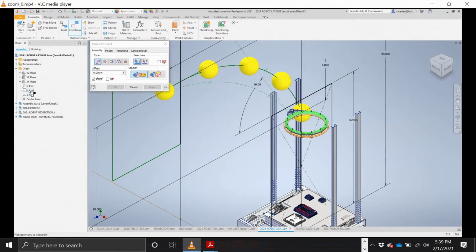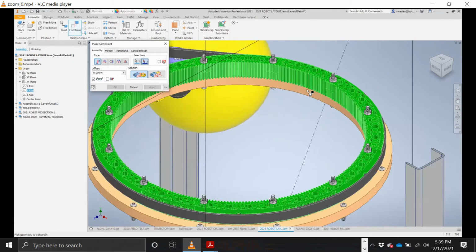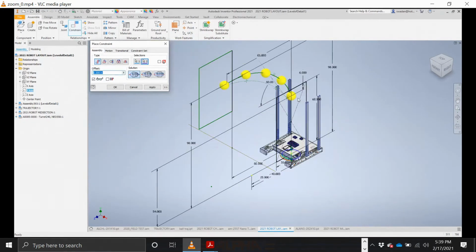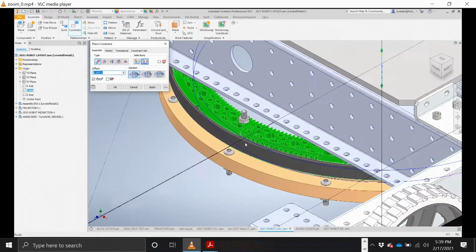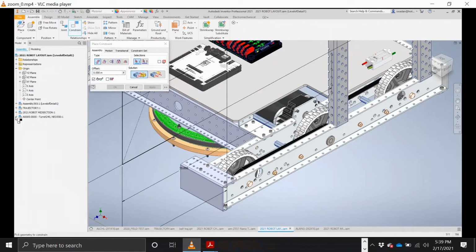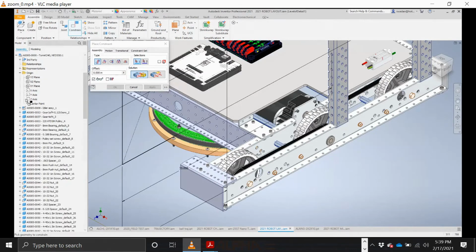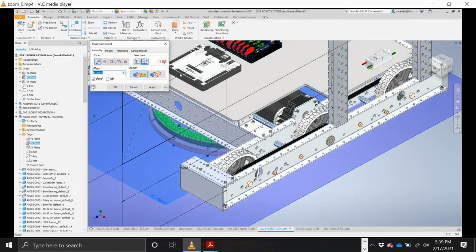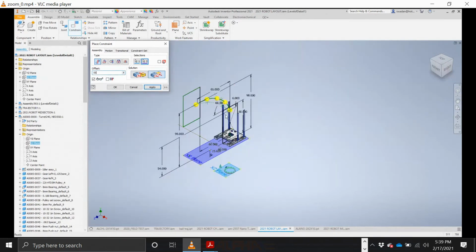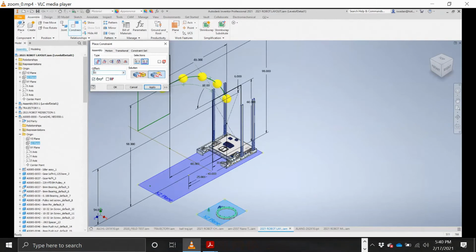And I put it where I want it. In this case, I'm going to be a bit lazy, and I'm going to take that turret and just mate it directly to my axis, and it moved out of the way, so I just need to create an offset for my z-axis, or my y distance, and we'll say about 55 inches.